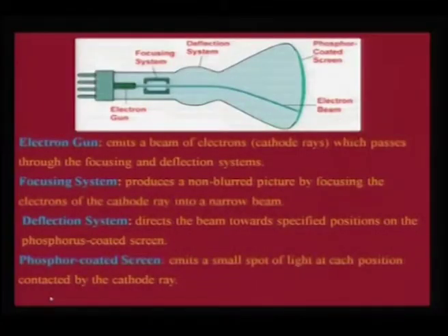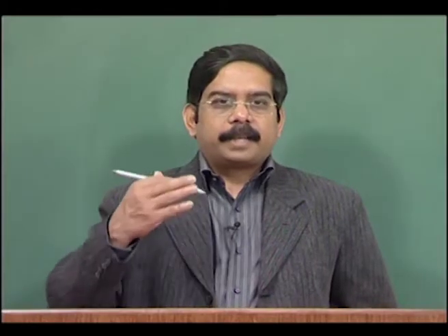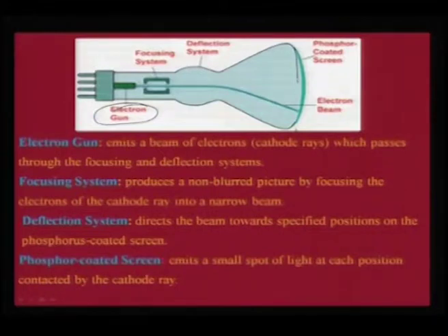Therefore, this is a simple contour of your CRT tube. This is your cathode ray gun, through which, using a deflection system, you can move this electron beam up and down. Therefore, it scans 100,000 times per second in such a fashion that you get a complete continuous display of your image, and in this place the anode is actually bearing your phosphor coated screen.